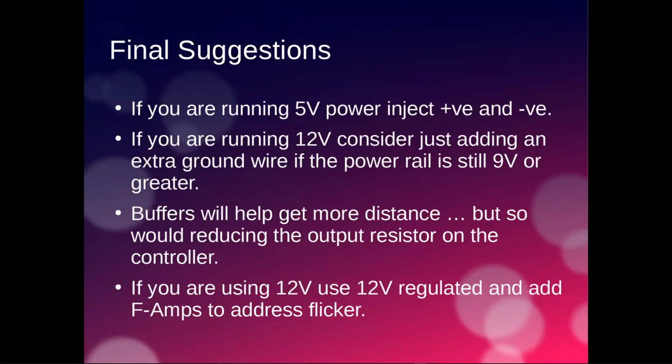So Keith, the 2801 data sheet says to use a 50 ohm resistor. Okay, there you go. In that case, yeah, put a 50 ohm. Presumably other pixels require other values, which may be why people try to find something in the middle. The way the Falcons work is they have one resistor network, and that resistor network governs two of the outputs, both the clock and the data output. So you're not going to be able to mix them up. You won't be able to have 33 on the data and 50 on the clock. If I were you, I would use the 50, because in my experimentation, the 50 was good enough.